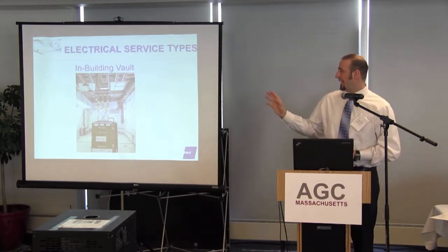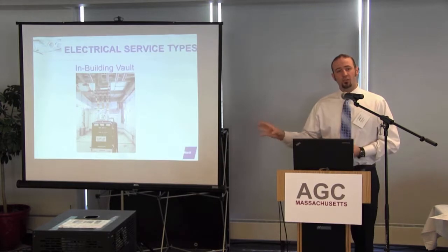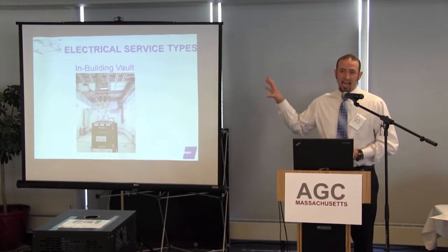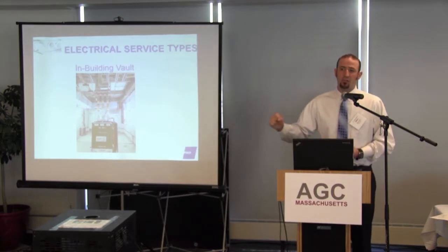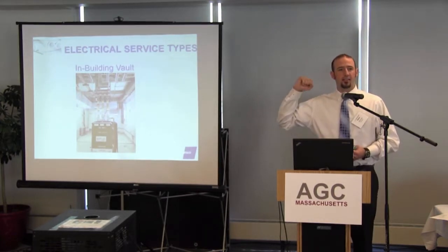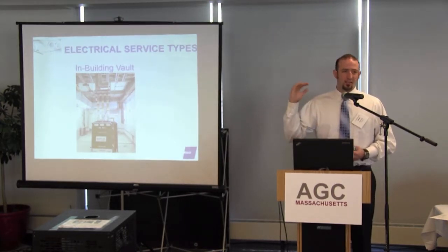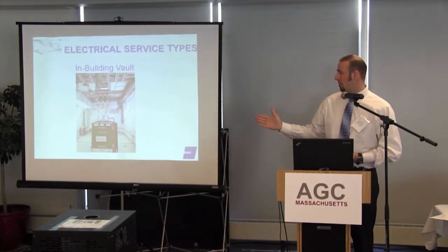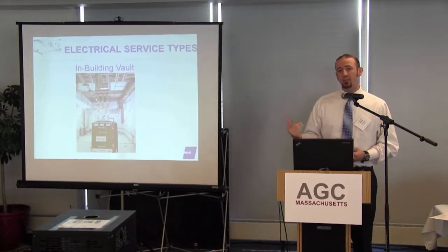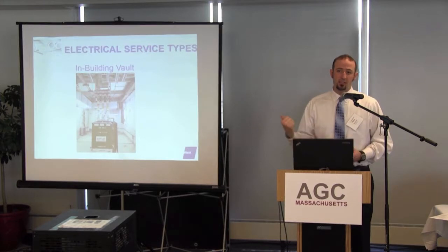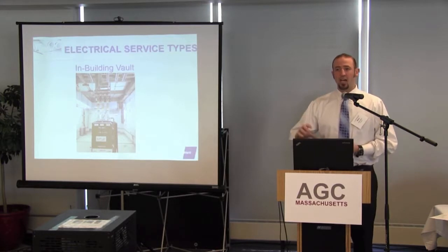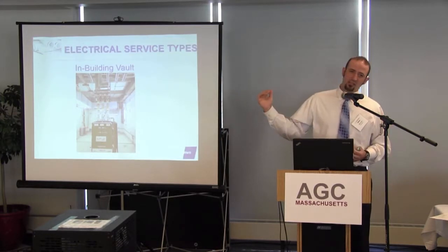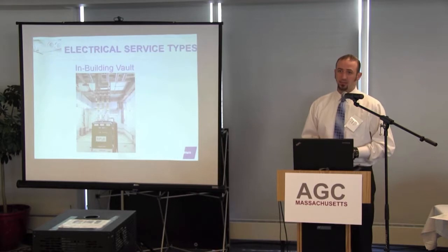So usually NSTAR will take about 6 weeks to re-engineer anything that's going to go into the sidewalks, because those sidewalks are full of water lines, steam lines, 13.8 lines. I'm actually working on a job right now on New River Street where we're submerging one of these things, and it is a hassle to coordinate with the building, and then you have to coordinate the inverts into the building.